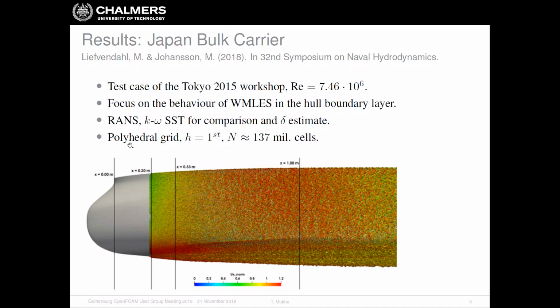And in this particular case, they've only created one grid, the polyhedral one. As we saw before, it leads to a smaller number of cells for a given volume and a given characteristic distance between the cell centers. In this simulation, they also sampled from the wall adjacent cells, so we can expect that there will be some underprediction in CF.